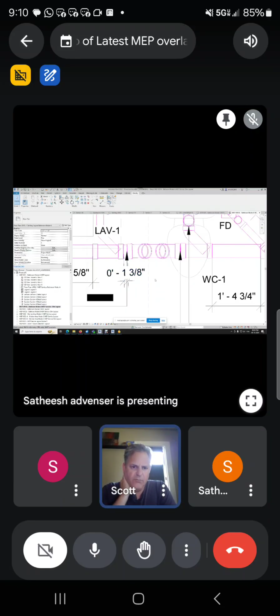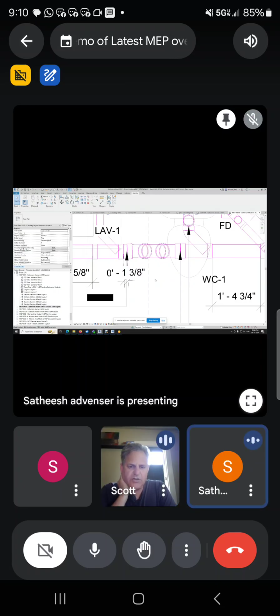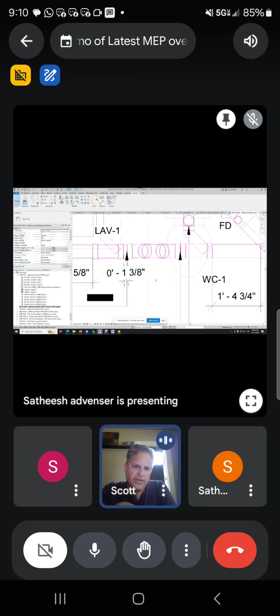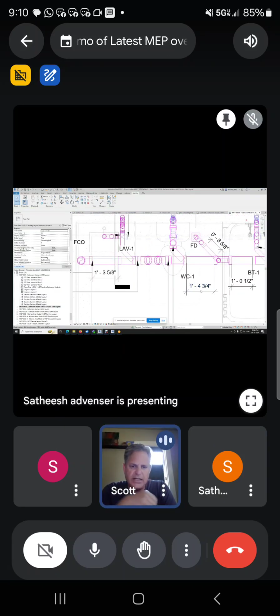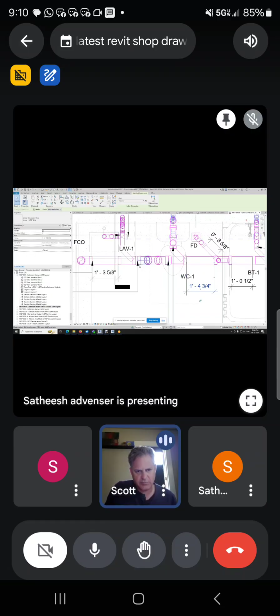Right. But we don't want to cut it to that. We need to add the flange to it, because it glues inside of it. In this area, only flanges are coming, right? Correct. So the 1 3/8 that you put, and I'm guessing on these measurements, it's going to be 1/2 inch on one side and 1/2 inch on the other side, or it could be 3/4. I don't know how far that 1 3/8 pipe is going to embed into that Y.